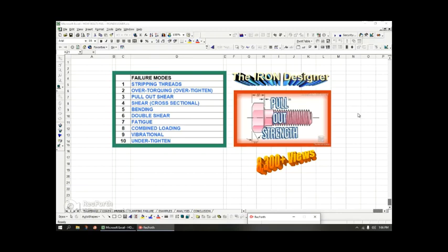You also have double shear, which is what you would have in a yoke pin or something on the shank. And you can even have triple shear. You just add an additional yoke to the first yoke, and now you can have triple shear. So there's many modes of shear. You could even have bidirectional double shear. You could even have bending stress double shear. You could have pull out double shear and bending. So you could combine these modes in as many ways as you can think of, and there are many more than this.